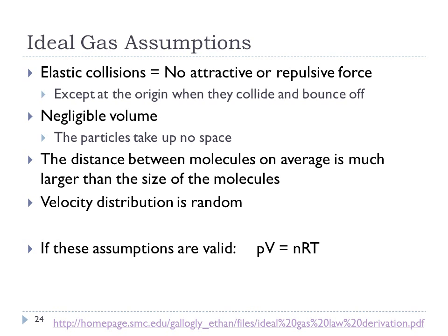Okay, so now we're going to move on to the next part of this lecture, which is where we start talking about ideal gas approximations and real gas modeling, when you start taking away some of the assumptions in the ideal gas model. So let's first go through and look at what all those assumptions are. So the first assumption is that all collisions are elastic.